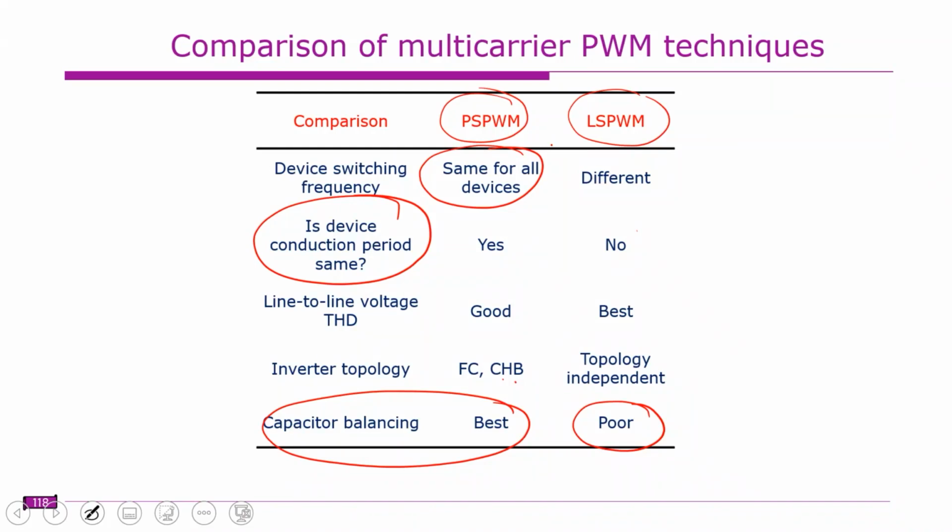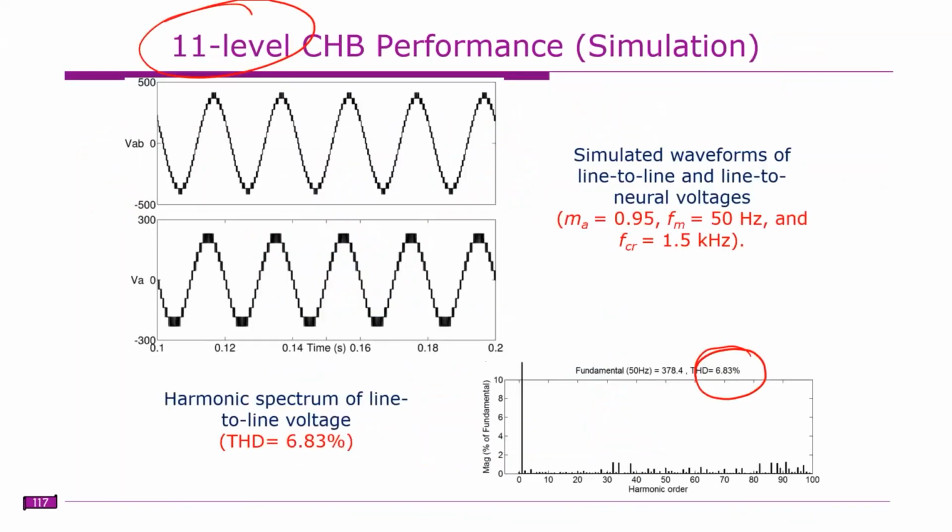We also noticed that in the case of phase shifted PWM, the sideband harmonics are centered at around (M minus 1) times MF, where M is the number of levels. In the case of level shifted PWM, they are centered around MF. So effectively, phase shifted PWM has an effective frequency that is M minus 1 times higher, which you can observe here.